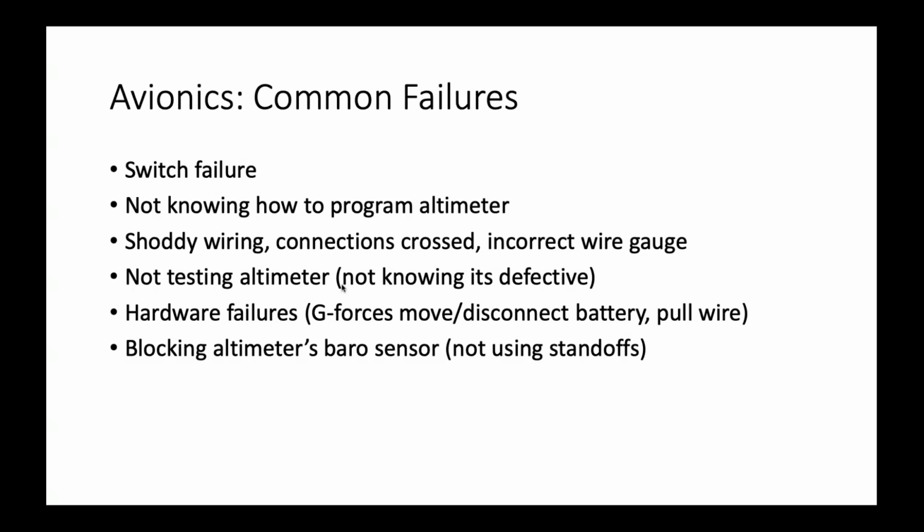So that's that one. And then some other hardware failures, like your rockets are going very, very fast, which will be exciting to see, but some other things that can cause problems are if you don't secure your 9-volt battery, or whatever battery is powering your electronics. If you say just put a zip tie around it but nothing on the bottom, and the G-force of the rocket just causes the battery to pull out the bottom or become disconnected in some way,